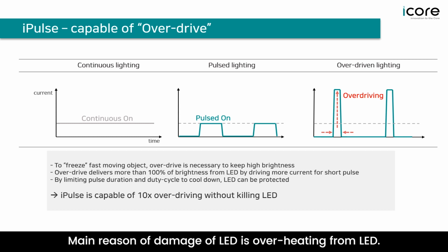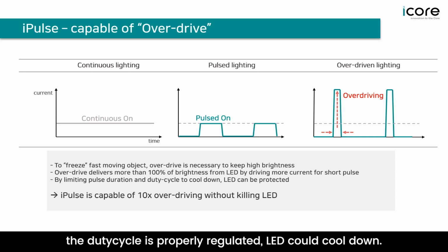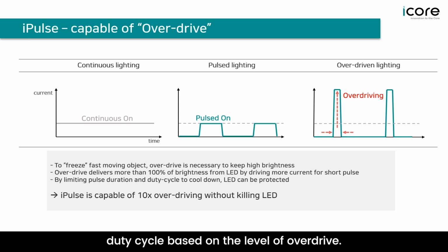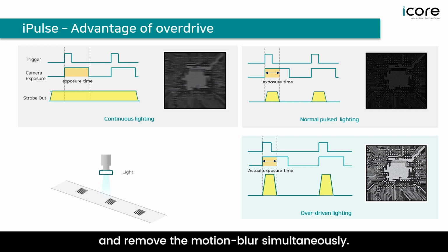Main reason of damage of LED is overheating from LED. But if the pulse duration and the duty cycle are properly regulated, LED could cool down. iPulse has a function to limit the duration and duty cycle based on the level of overdrive. Overdrive is a gift to those who wanna increase the brightness and remove the motion blur simultaneously.